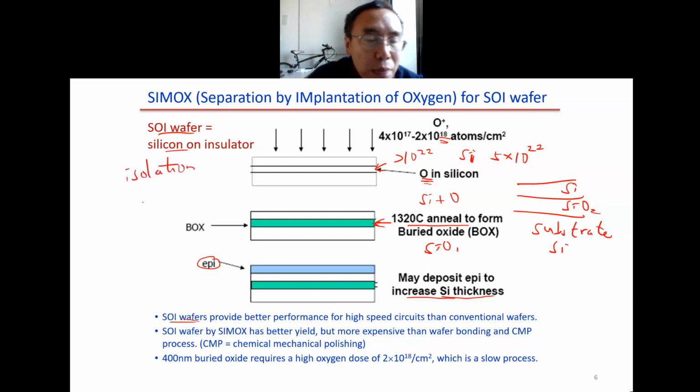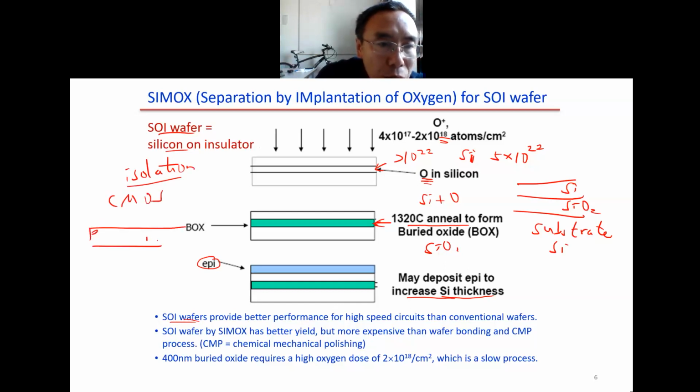In chapter 2, we talked about isolation between the PMOS and NMOS in CMOS. One way to do it is thermal oxidation. We grow a thick oxide layer to isolate the PMOS and NMOS. But even in this case, it's still possible for charge carriers to flow from one set to the other. That means the PMOS and NMOS are not fully isolated.